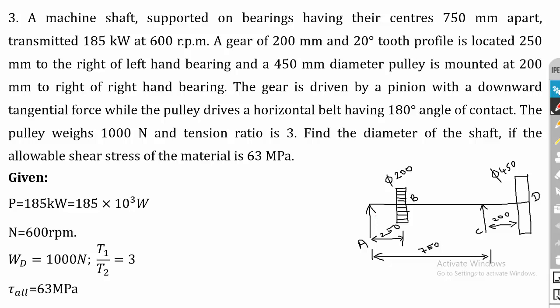In the previous lecture, we have solved a problem on shaft carrying gears. So, in this lecture, we are going to solve a problem on shaft carrying both gear and pulley. A machine shaft supported on bearings having their centers 750 mm apart.